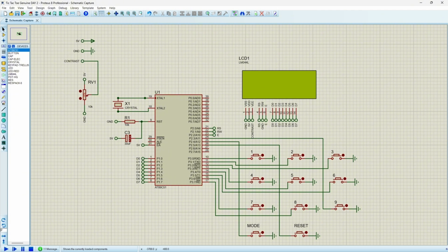So I'm just going to go through the components one by one. We were told to select an appropriate input unit, and we went with push buttons. We could have also used a keypad, but we did not because push buttons are inexpensive and we can get them anywhere. Also, each individual push button is connected separately, so if there is a fault in the circuitry, we can easily find it. That is why we went with push buttons.